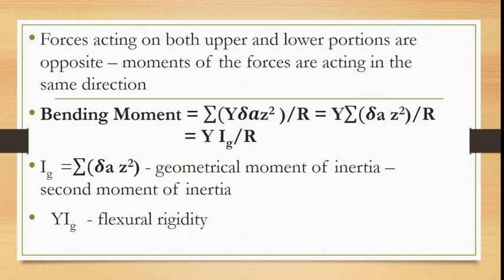So in this class, we had derived the expression for the bending moment. For that, we had considered a beam in which the upper layers undergo elongation and the lower layers undergo contraction after bending. Initially we found the expression for strain. From that we calculated stress, and from that we got the expression for force.